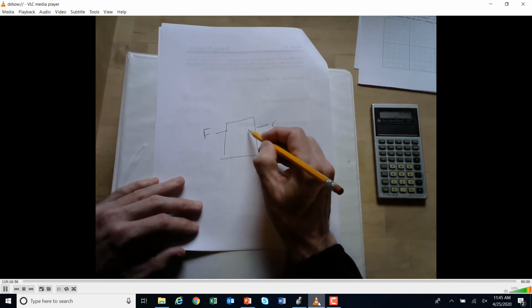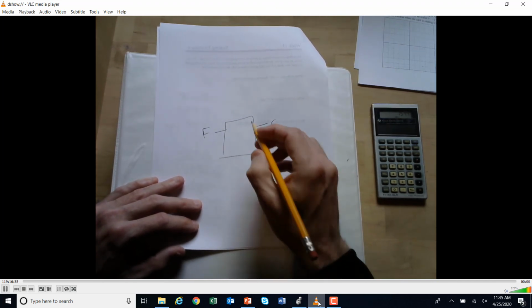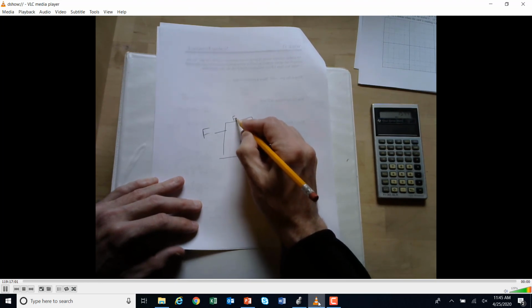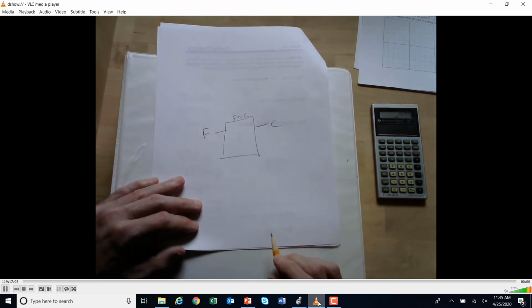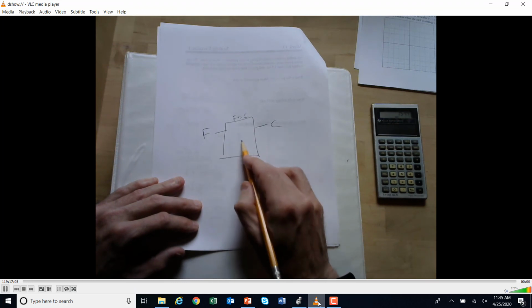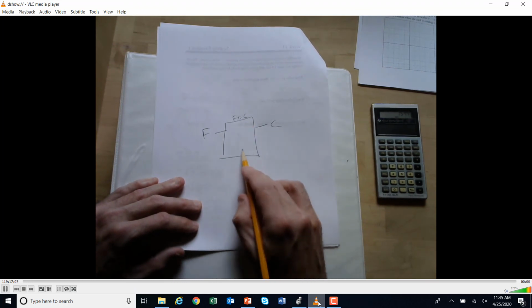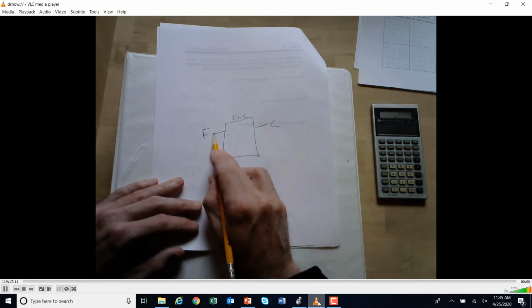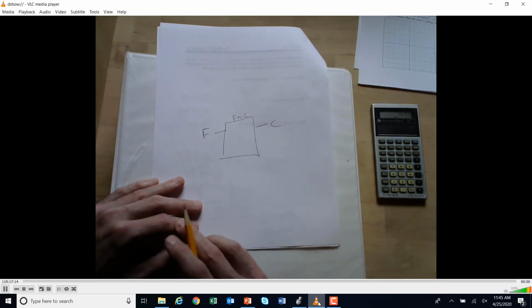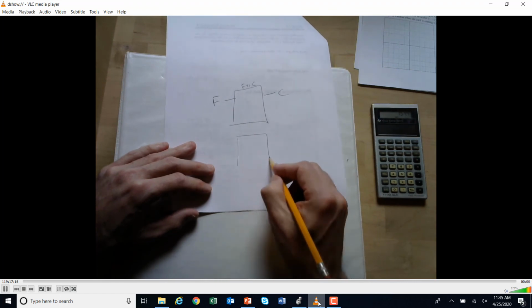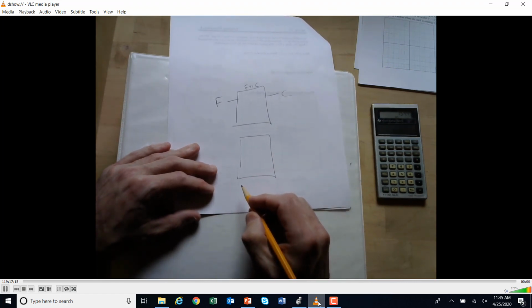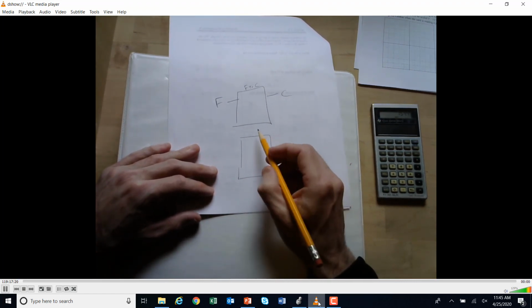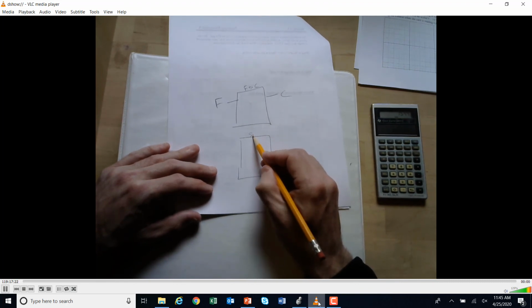And this is the ladder logic that will be put in here, and then this will have a command called F to C, and you won't be able to see the logic there. You can click it and see the logic, but it's just going to come on as an add-on instruction, so that whenever you put in this, it'll automatically generate that. You can make much more complicated add-on instructions, and we're doing one called scale with parameters, okay?